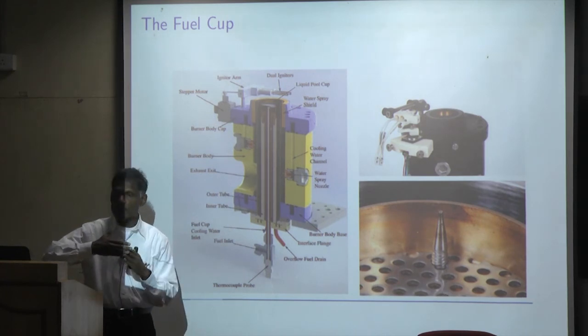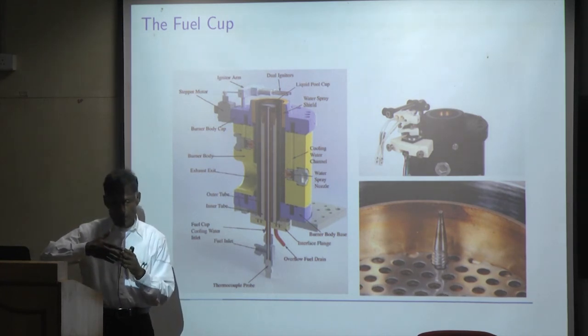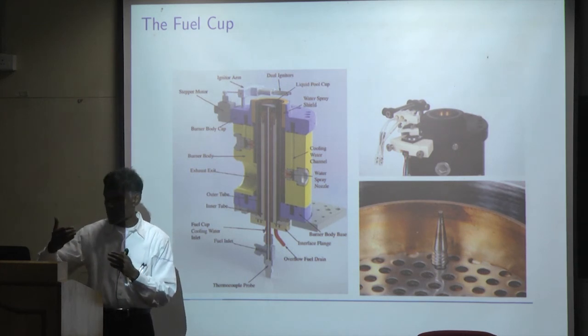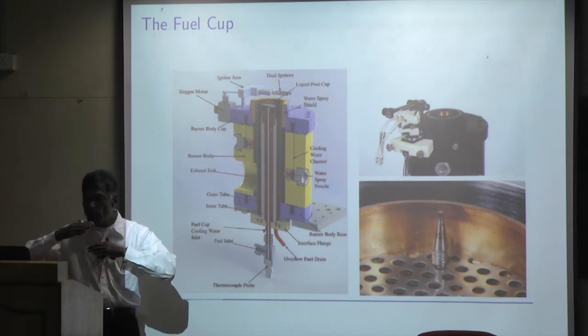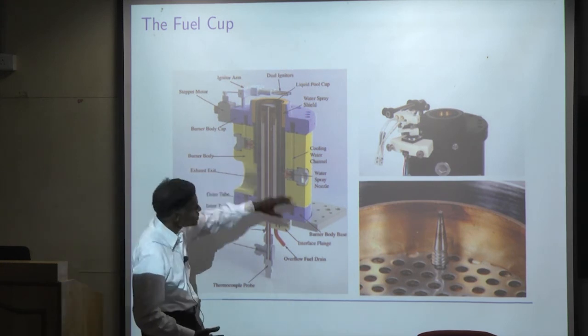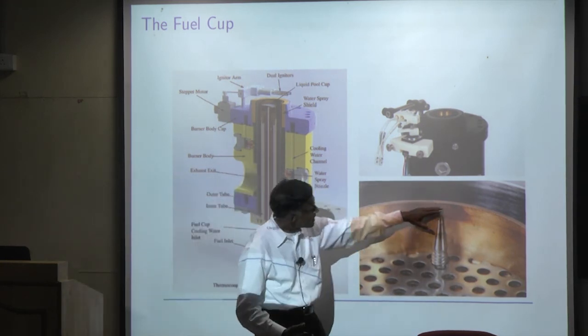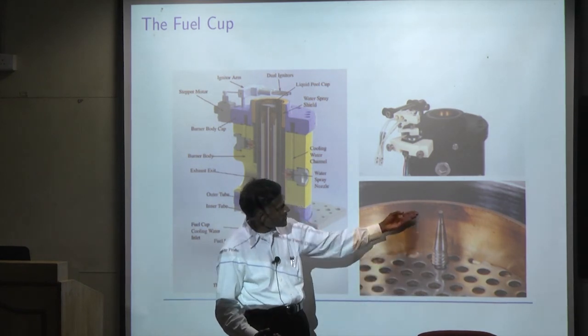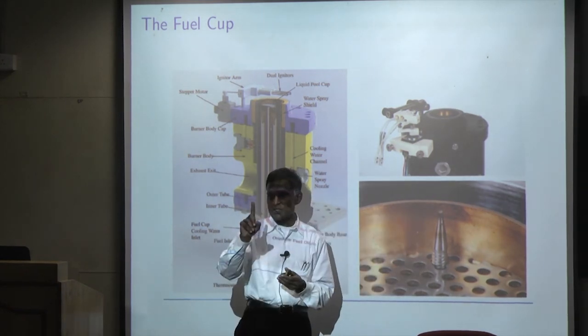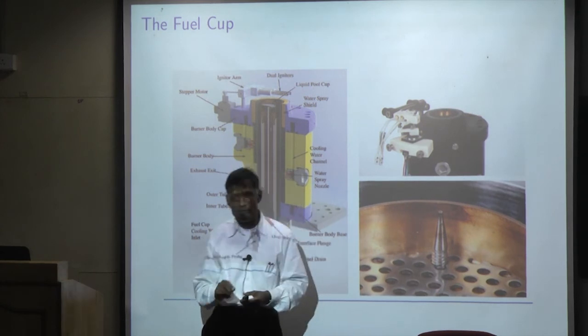When you pre-vaporize them, there's a problem because with increasing pressure the boiling point goes up. If you heat them too much, then of course you have breakdown. So we did experiments on the liquid pool. This is the liquid pool. The fuel is introduced from the bottom, and this pointer tells you the surface, how to maintain the level of liquid.